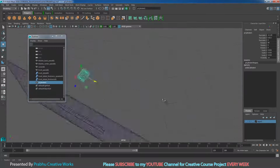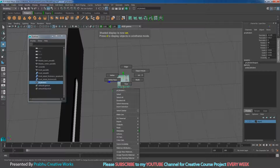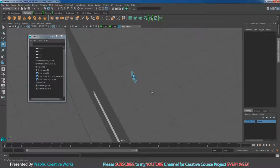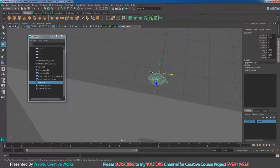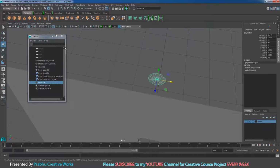Go to perspective, press 5 on the keyboard, right click and choose face. So select the back face over here and press delete on the keyboard. So right click and choose object mode. I want to make the center pivot. So go to modify and choose center pivot.